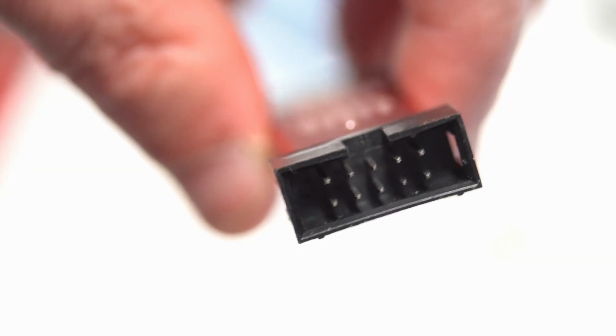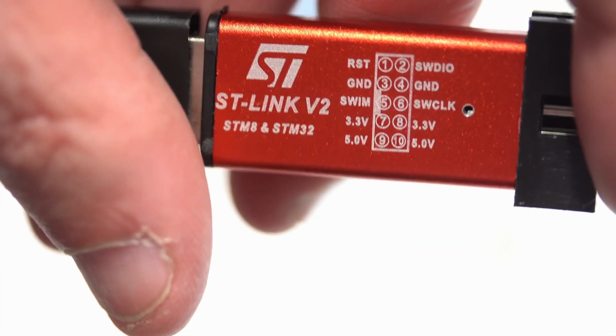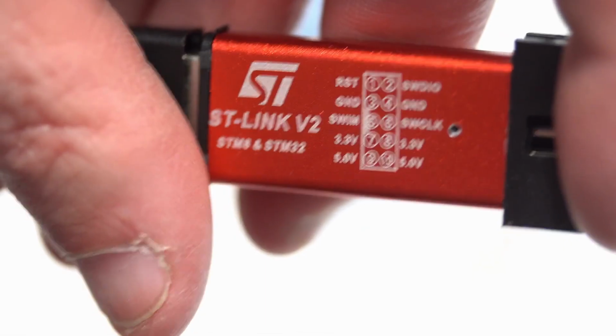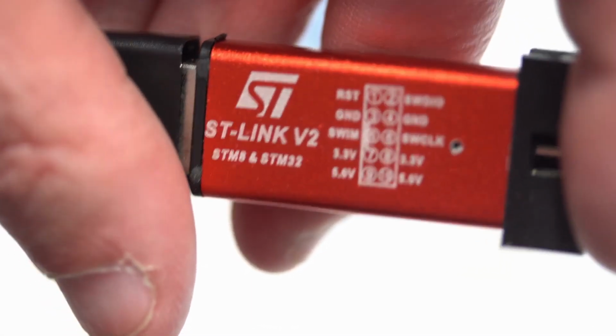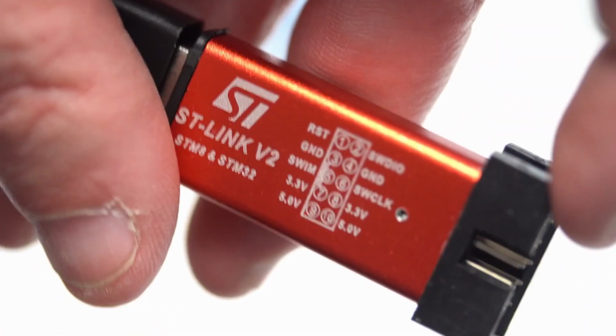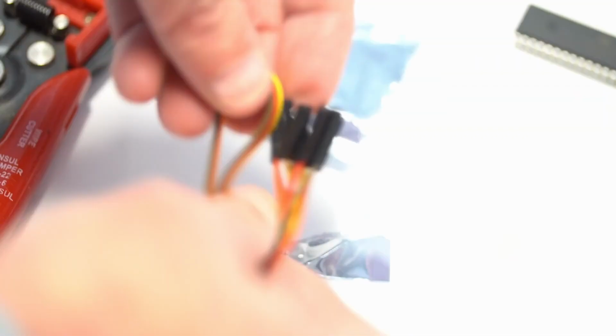The device that allows you to connect the computer to the STM32 microcontroller is the programmer, and it allows you to send the programs that you create to the microcontroller. The programmer also allows you to connect the microcontroller to the STM Studio to monitor the variables that you wish, to graph the variables that you wish, and also to debug the program while it's running. ST also make a programmer like this you can purchase if you're looking for something that is directly from ST Micro.